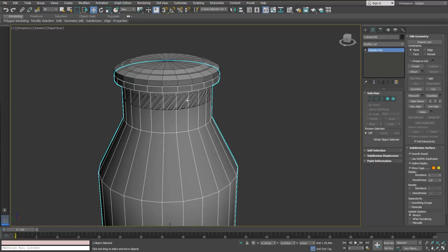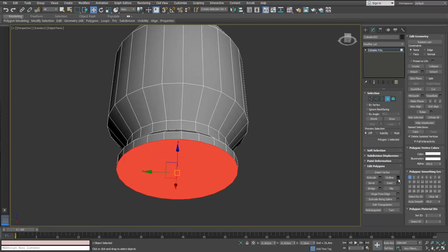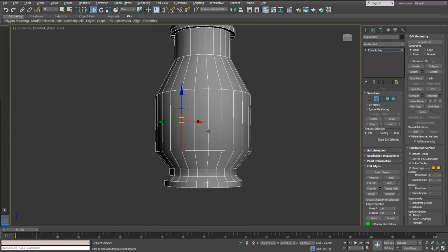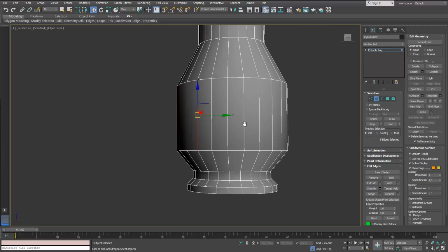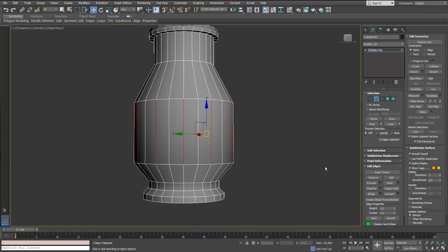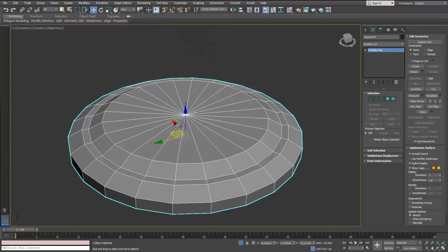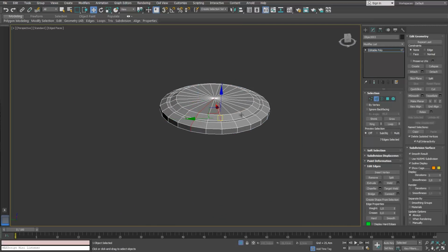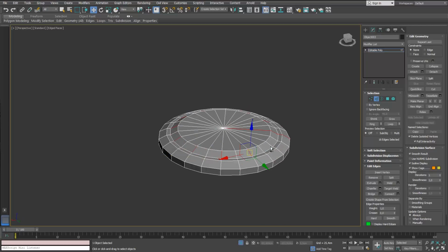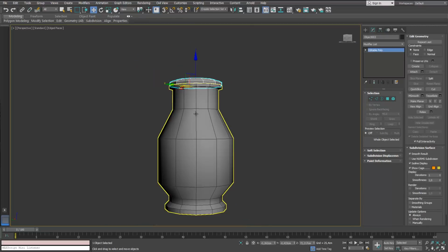So first of all, we're gonna remove the floating geometry, because it's not necessary, and we're gonna remove some of the extra edges that are not needed, even though it's gonna be a little bit more than we should put on a low poly model, but on the other hand, keeping it as it is would be a little too much as well. So I'm gonna choose to reduce the poly count a little bit, even though it's gonna look a little bit less smooth than it's supposed to be. Okay, Control Backspace in order to remove the edges, by the way.